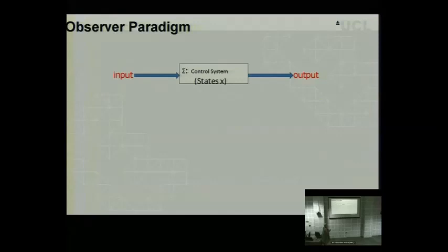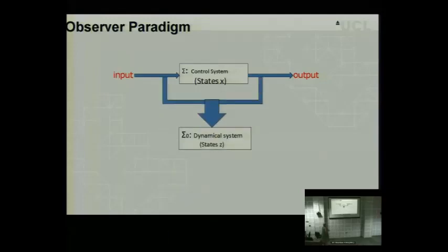We're lumping in all the things that may be going on, so the system open loop, the system closed loop, we're calling it the system. Here we're interested in the observer. So we're interested in putting a dynamical system there, just as we did in our MATLAB block this morning. We added that extra system which seeks to estimate those states, and we call it an observer.